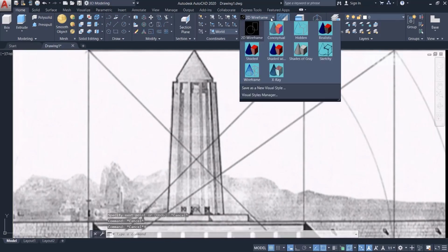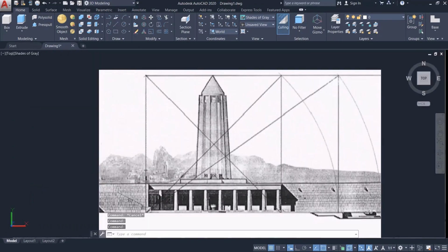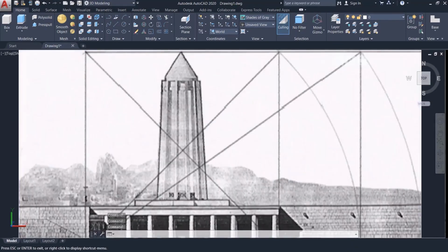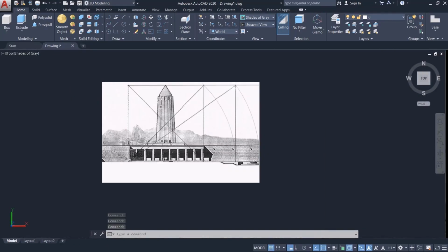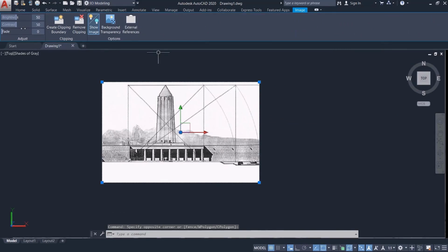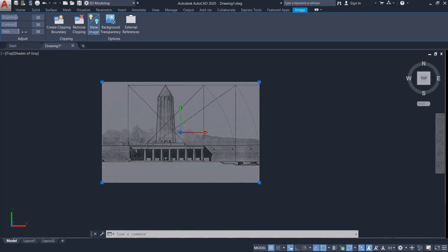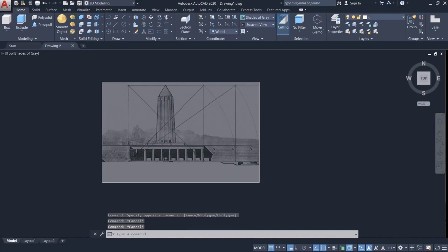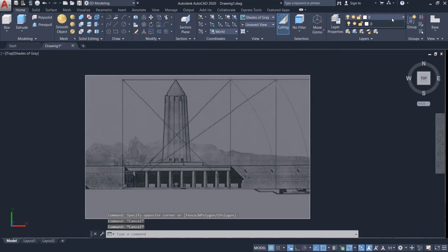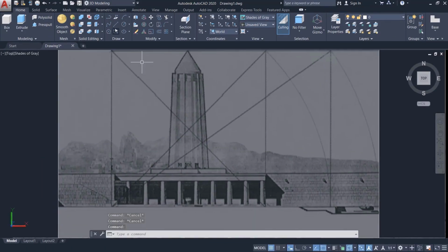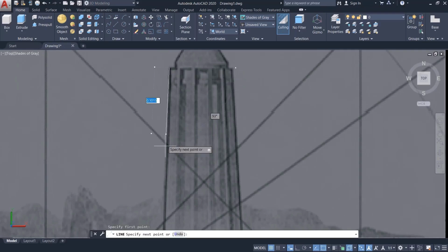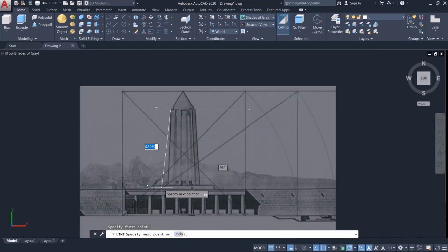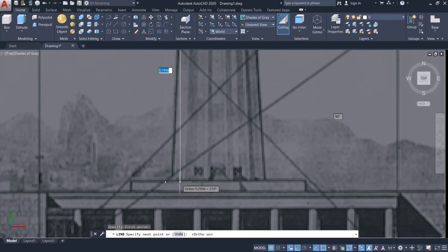The first thing we should do is put this on a sheet of gray, so it doesn't keep freezing up. And then, so I can see the lines I'm drawing on it, I select the image. This ribbon context menu opens up here at the top, and I increase its fade. I increase its transparency so that I can do my own drawings here. Now we can see our line better. I turn on F8, and draw a line from the top down to here.